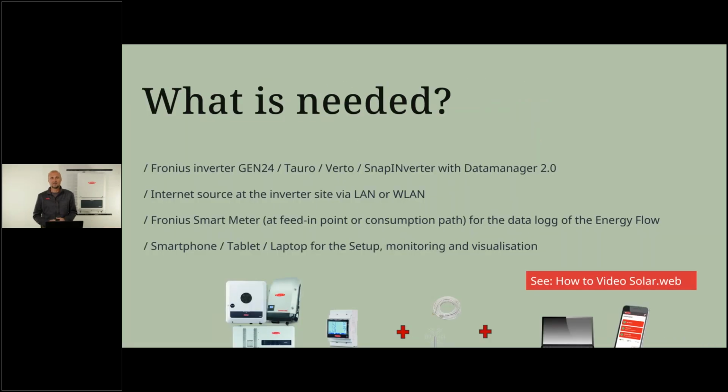So what is needed to do so? Basically, you need a Fronius inverter, can be Gen 24, Tauro inverter, or Snap inverter with Data Manager. Of course, the system must be online, connected via LAN or Wi-Fi to your internet router.